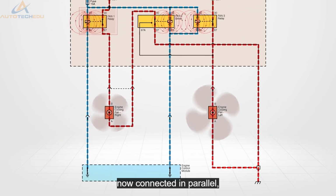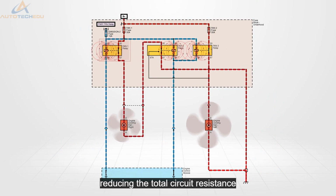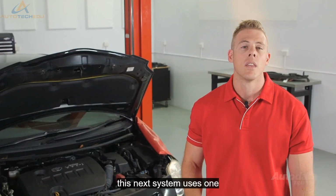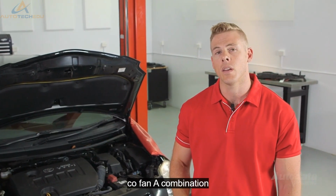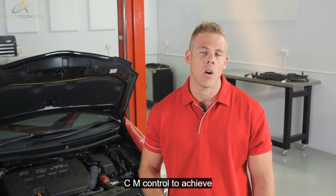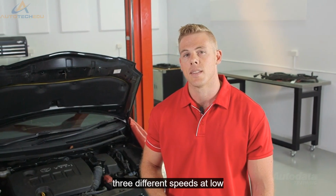Both cooling fans are now connected in parallel, reducing the total circuit resistance. This allows maximum current flow through both motors. This next system uses one cooling fan, a combination of relays, resistors and ECM control to achieve 3 different speeds.